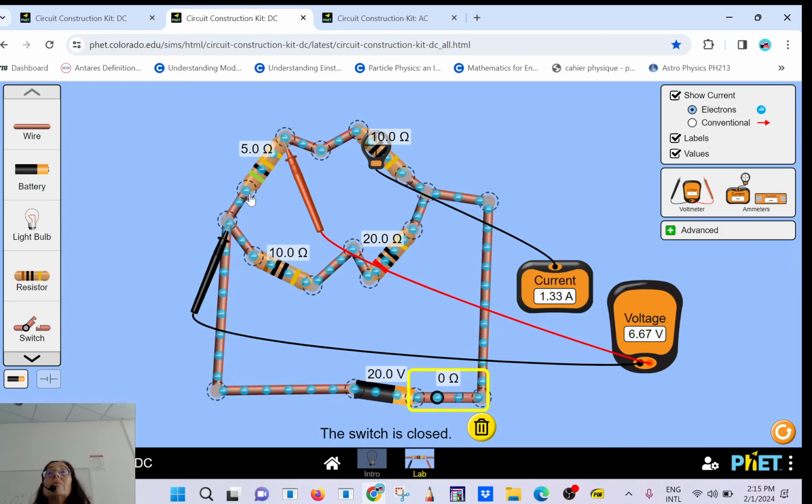Here the power supply is 34 volt, but that is the peak value. Can you find the RMS first? You need to find the RMS voltage, the RMS current, and the average power. You can use Ohm's law as long as you use the RMS voltage and the RMS current. Otherwise, you can't.